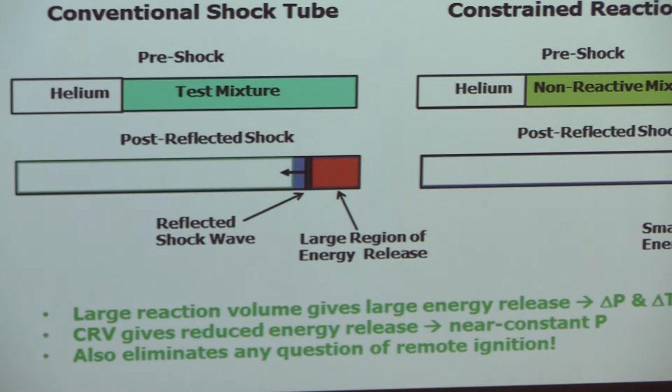You can go into ChemKin, which is the routine people use, and you can specify the initial condition. And assuming that it's adiabatic, you can specify pressure versus time. One limit is the pressure is constant. So you can specify constant pressure, or you can specify the pressure, and then you can model it.